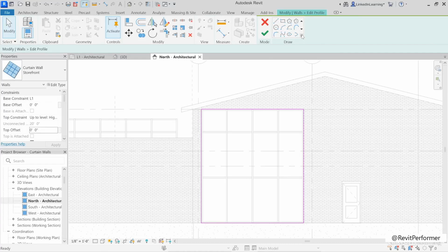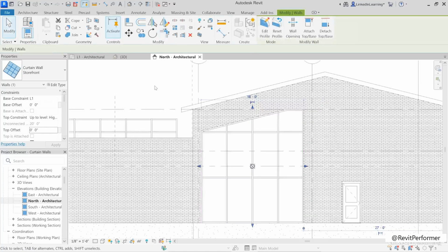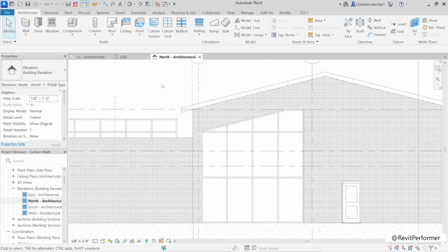I'm going to open up my toolbox here and choose the Pick Lines. I'm going to couple that with an offset of 4 feet imperial or 1200 millimeters metric. And I'm going to offset a line down from the underside of the roof. Then go to Trim and Extend and trim this corner and this corner. Click Finish.